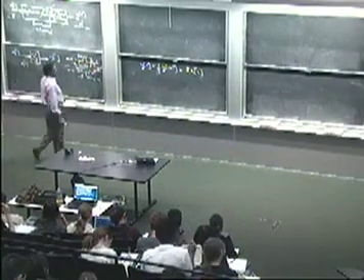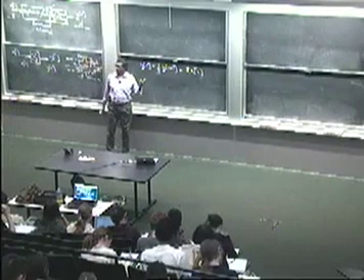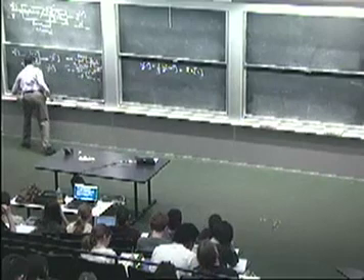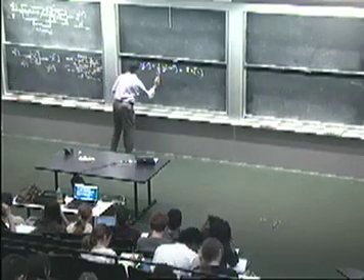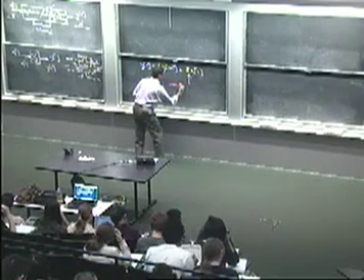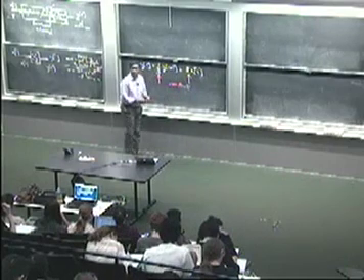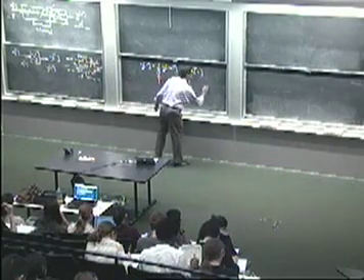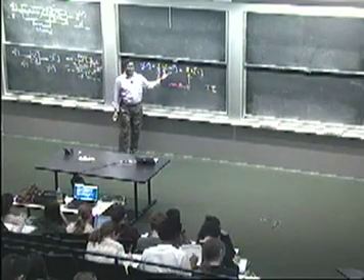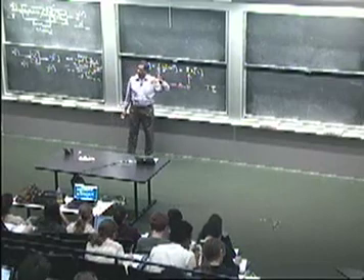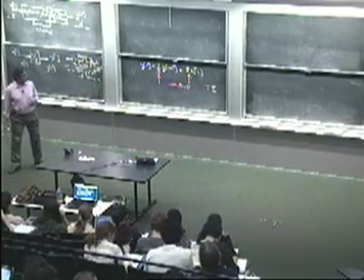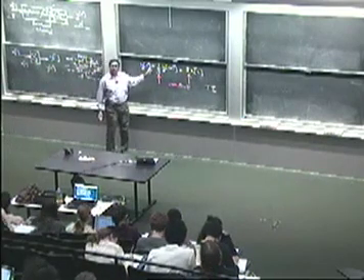Okay, so time invariant because the law by which you're composing things to get the output doesn't depend on time. So the point is that these coefficients are constant. Because these are constant, what you have is actually a time invariant system. To get the output at any time, you're taking 1/3 of the output of the previous time plus twice the input at the present time. And that prescription holds along the entire time axis. So the actual value of n doesn't matter.